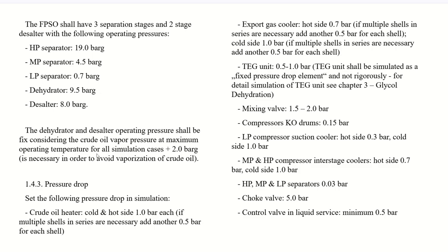This is the typical pressure drop across equipment, like a crude heater, cold and hot side, 1 bar pressure drop. So basically these pressure drops are used for the simulation case, like how we determine the pressure drops in the equipment, and accordingly you can determine your pressure profile from the suction to the discharge, and accordingly